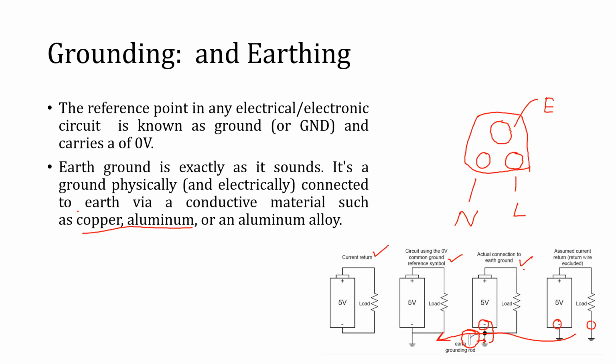If the main power supply is further connected to earth, that is well and good. So these are some of the configurations we use in signal conditioning and data acquisition, and a transducer must be connected in such a circuit which should be at least grounded with the power supply. It should not be a floating circuit like the first example. We'll see what the disadvantages of these circuits are in the next slide.